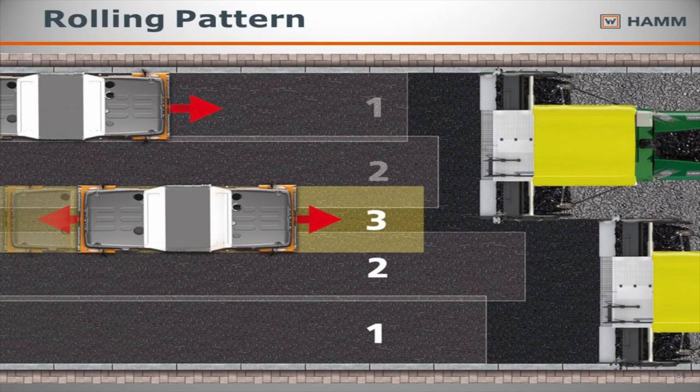This one here, paving an echelon, this third pass is going to alternate between each roller when they're done with their pass, so that the third pass is always being altered by each roller. If this roller is doing all 3 passes, this guy's going to be doing a lot of sitting. This guy's going to do a lot more working, so we always alternate the passes.